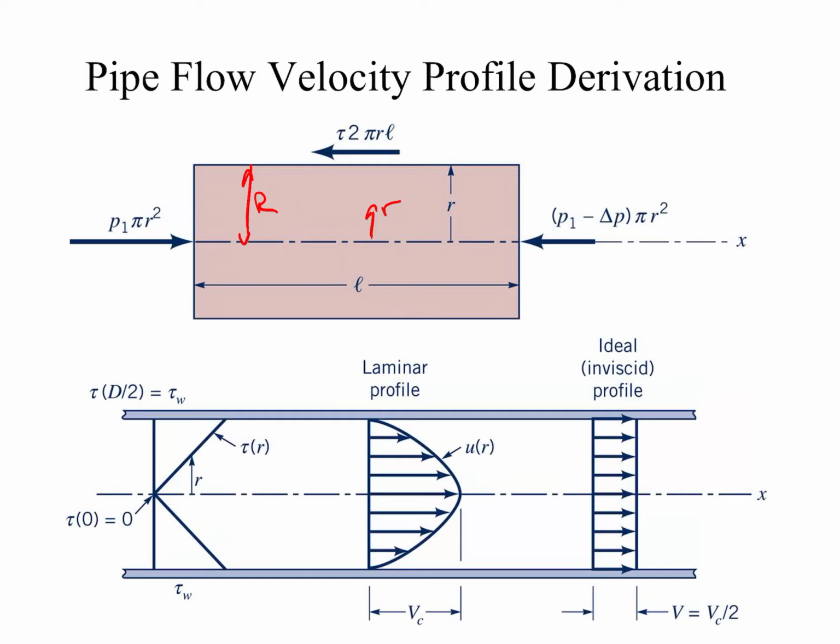We have the pressure on the left-hand side and the right-hand side. And since the wall is continuous, we don't have separate walls, so we only write down the shear stress times the area on one side of our element, which is acting against the force of the fluid moving from left to right.